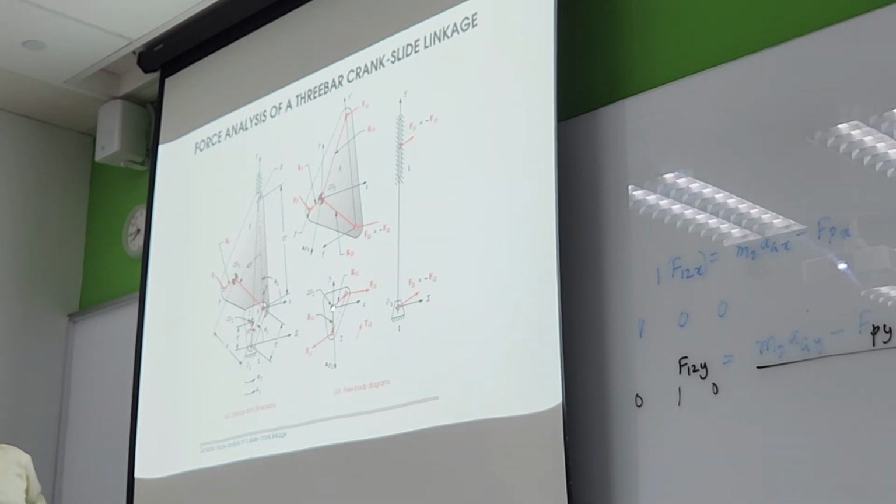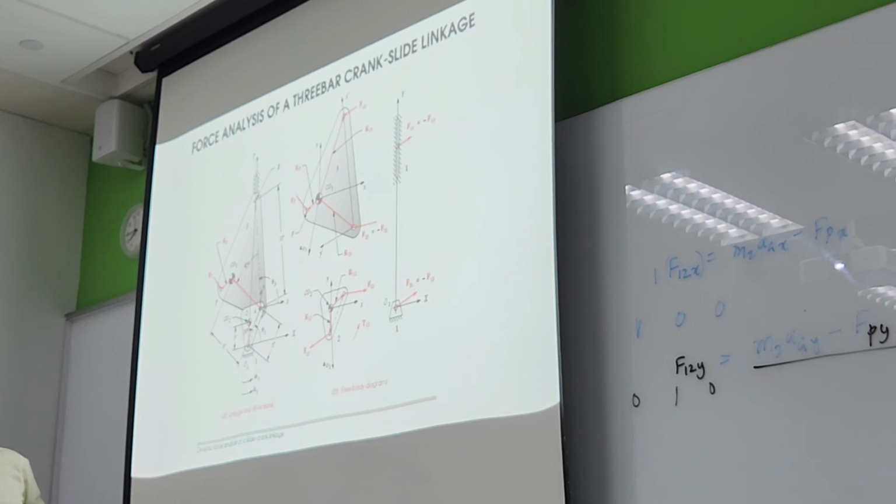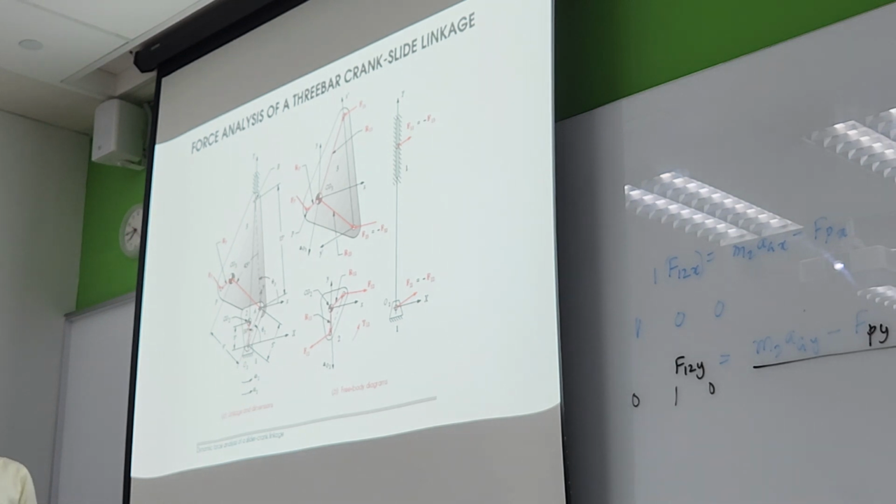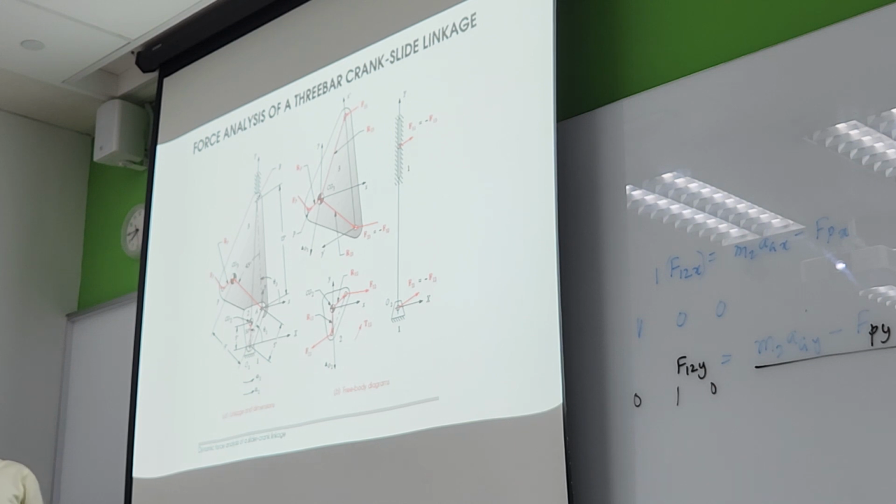So we are locating the centroid for link 2 and the centroid for link 3. Consider mass is known, and all the geometry is known. So the force acting on this point, 32, we can calculate. Now, is the free body diagram part clear to you? There is a 4-bar linkage mechanism, so you are going to draw it for the 4-bar.